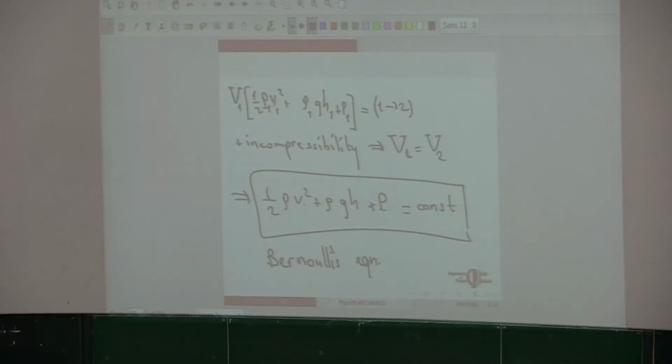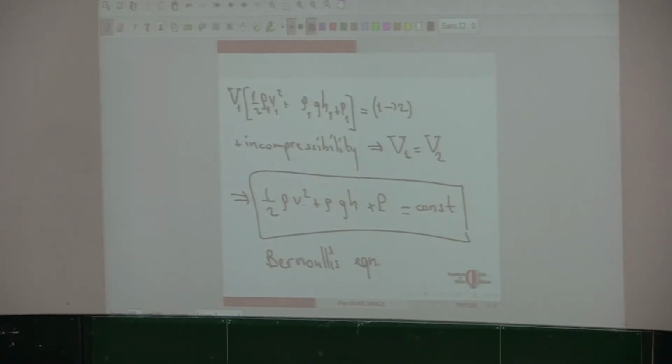And then at this point, at this volume, he is increasing the velocity, the speed. If there is a larger speed over there than from here, then the pressure over there should be less than the pressure over here. But the pressure over here and the pressure at the bottom part of the paper are equal, because the air at the bottom of the paper is not flowing. It's constant. So if you look at the foil only, the pressure on the top is less than the pressure on the bottom, because the velocity on the top is larger.